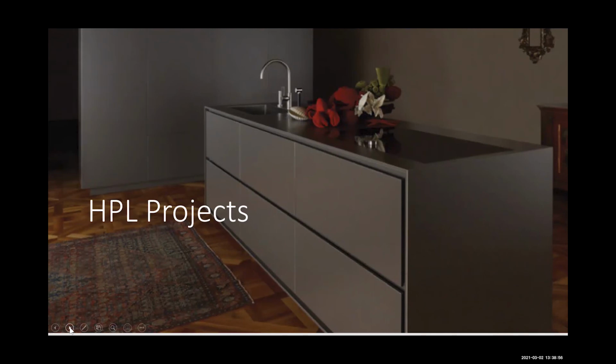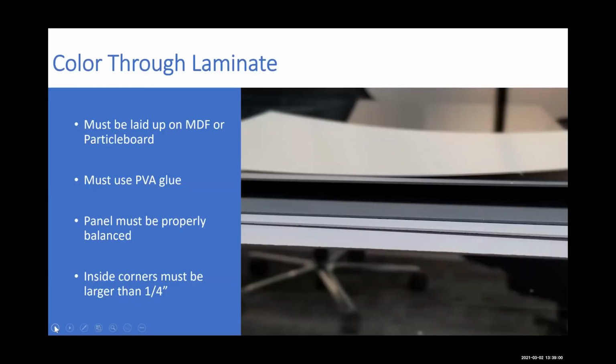When you do full color through, you cannot use plywood as a substrate, and you have to use PVA glue. And it has to be balanced equally. Typically, full through colors are a little bit thicker than regular laminate, so your backer panel has to be the same thickness, or you will get cupping.